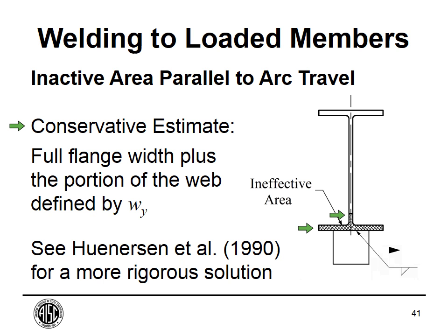Now, once again, I use section modulus on this, so it's going to give you a strength that maybe is 20% of what the full beam strength is. But remember, that doesn't mean that you can't do this. It just means that you're going to have a smaller load because your preload is not going to be equal to the total load on the beam.